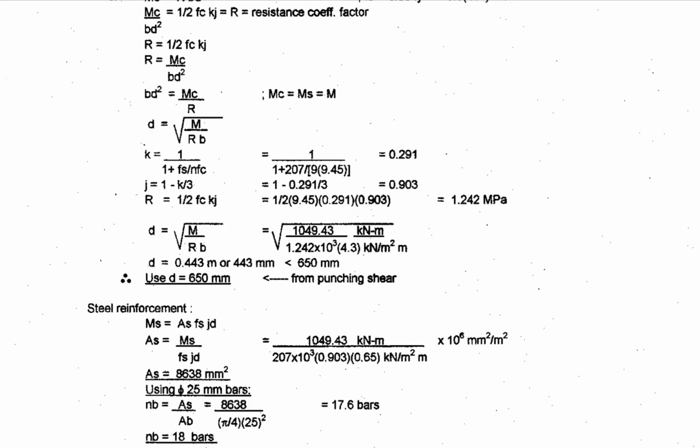So if the rebar diameter is not given, maybe you will use 25, but the standard or the minimum bar diameter used for footing is 12 mm. Okay, if that is not given in the problem, you can use 12 up to 32 or 40 millimeter. So it's up to you what diameter you use in your design. But normally you have to design it with common sense.